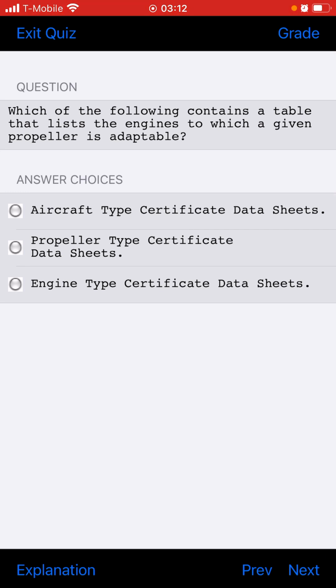Higher than normal fuel flow indication. The principal fault in the pressure type fuel flow meter indicating system installed on horizontally opposed continuous flow fuel injected aircraft reciprocating engine is that the plugged fuel injection nozzle will cause a higher than normal fuel flow indication.